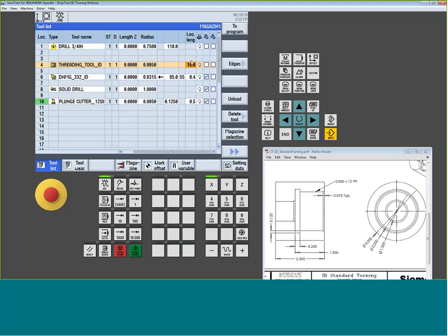Well, on some versions of software, we weren't converting this number properly when it came to simulation. So what would happen is we were looking at the number and treating it as a metric value, even though I'm in an inch mode. So if I left this and put a more appropriate value of like 0.5, you're going to see this tiny little insert's going to come in.